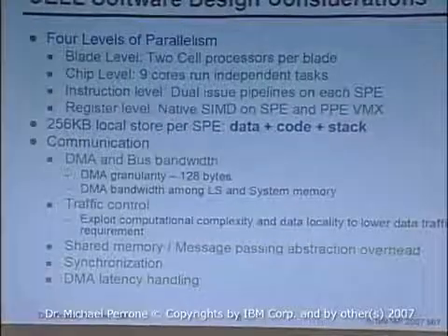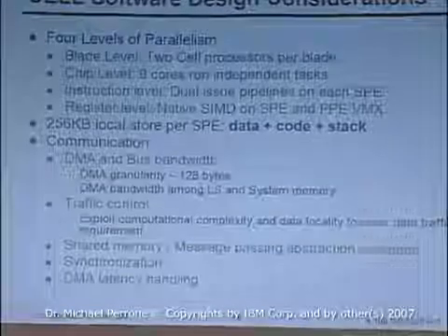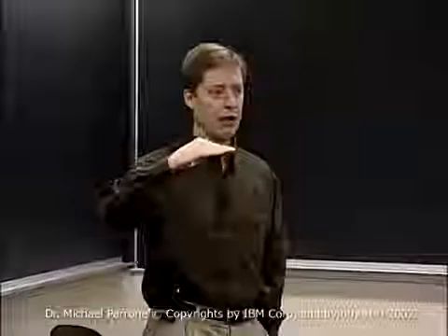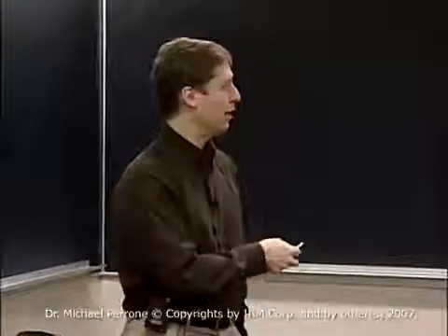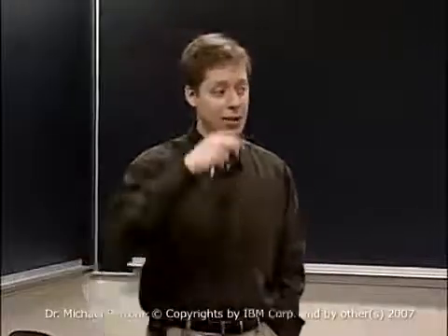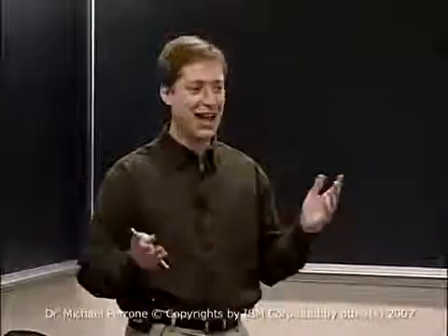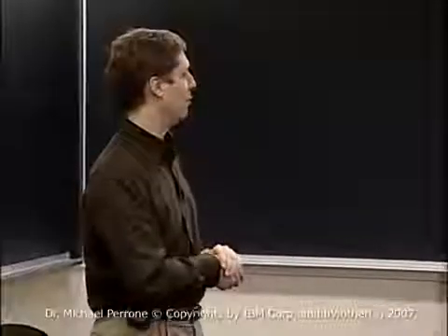Now, there is a memory management library, a very lightweight library on the SPE, and it's going to prevent your data from overwriting your code. Because once the code's loaded, that memory management library knows where it is, and it will stop you from doing a malloc over this code. But the stack is up for grabs. And that was again done because of power considerations and real estate on the chip. If you want to have a chip that's this big, you can have anything you want, but manufacturing it's impossible. So things were removed, and that was one of the things that's removed, and that's one of the things you have to watch out for.